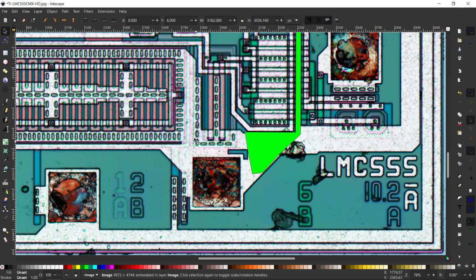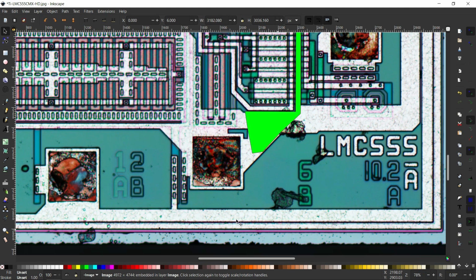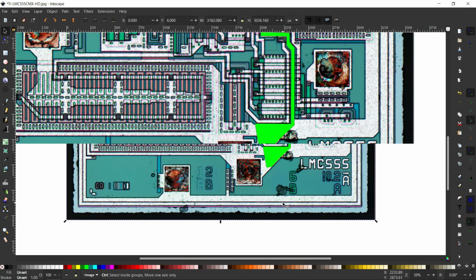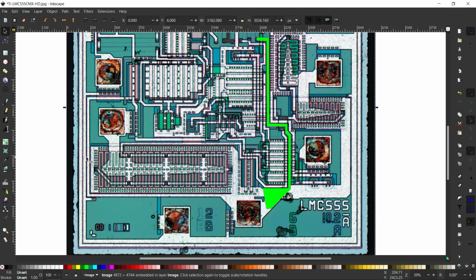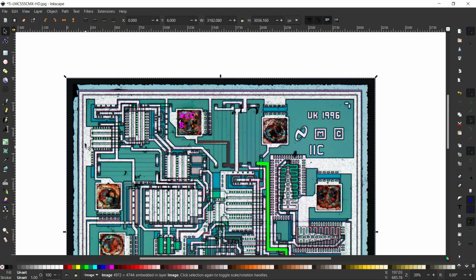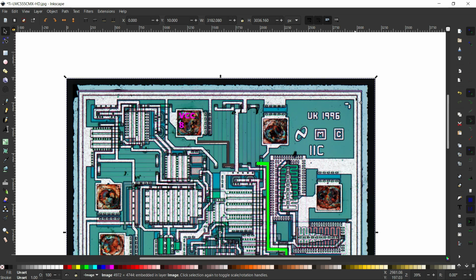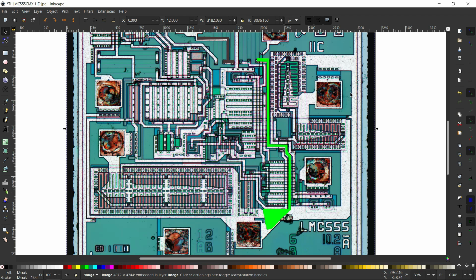So here, hopefully you can see how much metal width there is for the ground pad, and it also consists of an ESD diode. Completely around the chip is connected with the ground signal. So around the chip, the inner white line, hopefully if you are following my mouse pointer you can identify the inner line, wherever it is going, all of it is ground, everything is a ground pad.